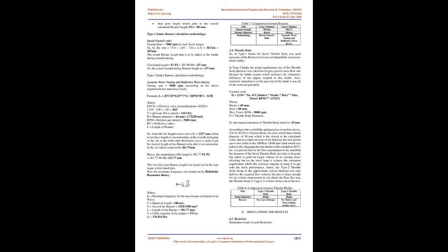3.2 Plenum. Engine swept volume, 373 cubic centimeters, common for both. Type 1 intake plenum volume, equivalent to the stock air box value of the bike, equals 3000 cubic centimeters, equals 8 times the engine swept volume. Type 2 intake plenum volume, 3150 cubic centimeters, equals 8.4 times engine swept volume.